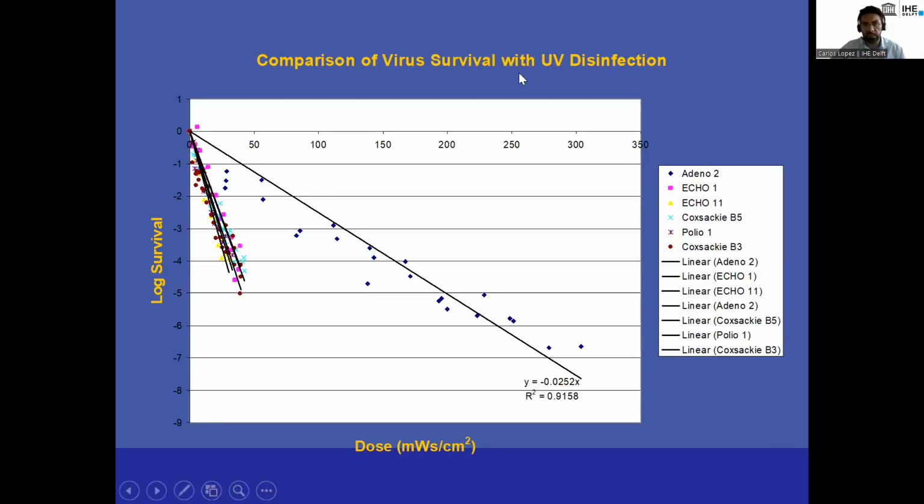With this, we finish, and we can continue with the design exercise. So these are some values. I gave some information about the importance of these pathogens, or the relevance of the removal of these pathogens. And with the values that we have discussed, now we can do some calculations to estimate what are the conditions that we need to lead to the inactivation of these organisms from the water. Do you have questions?